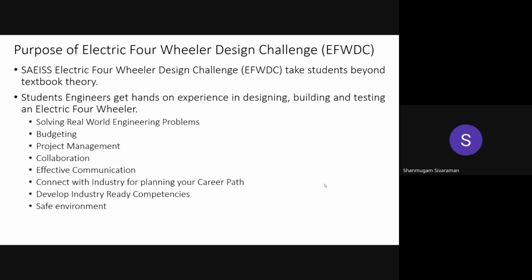First look at whether the wheels are turning. If the wheels are not turning, then go to the propulsion system, basically the motor. If the motor is okay, then go to the energy storage, basically the battery. If all these things are fine, then look at the cables and the switching circuits. So this goes by a process. That's what I want to impress upon you.